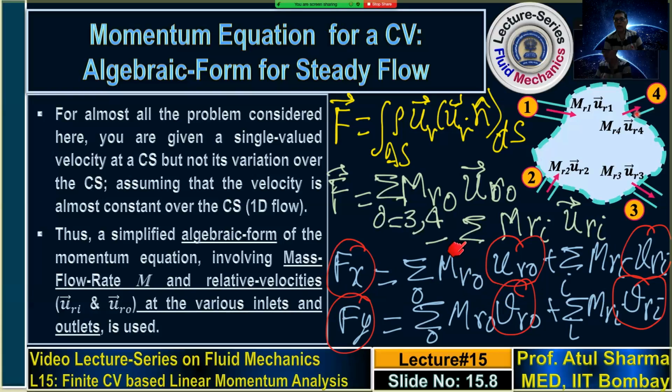But outside the box or the circle, the terms that you are having are basically the mass flow rate. And remember that if the control surface is vertical, then the mass flow rate will involve the normal velocity u, and if the control surface is horizontal, then it will be v. But in general, it is not horizontal and vertical. And in that case, this mass flow rate will involve the normal velocities. So note the difference between the velocities which are involved in the mass flow rate and the velocity that you consider for the calculation of the x component and y component of the forces.